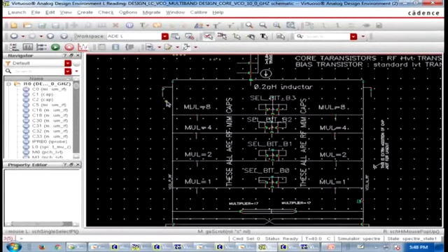So here, maybe the phase noise requirement is not that stringent because we don't have any adjacent channel interference, which is present in wireless communication, because it is all guided media. But the fact is that this should run at 10 gigahertz, and another thing is the power, but mostly the frequency here.